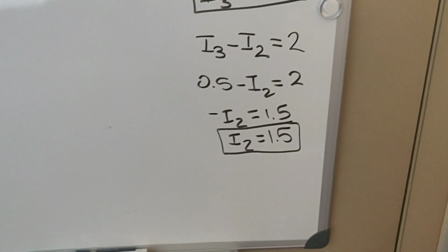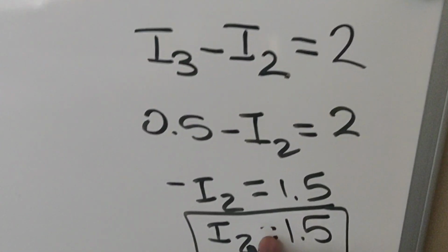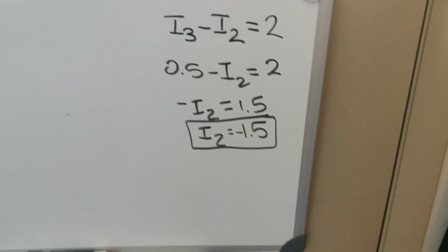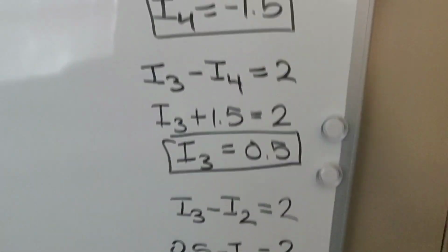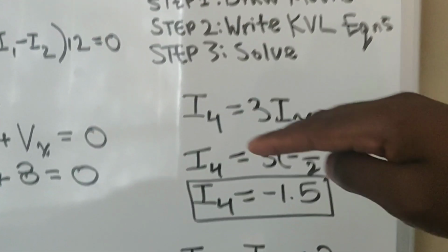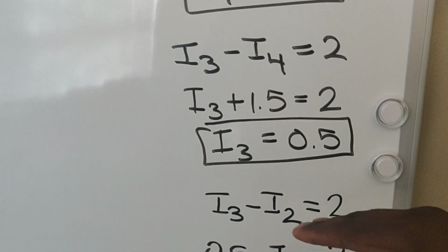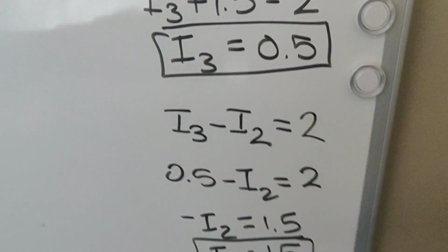Yeah. So I went ahead and just finished a little bit of algebra on that, and we finally come to, actually, this is a -1.5. So we finally come to what we needed. We found what I2 was after starting back from I4, analyzing the circuit, and drawing equations to solve for the unknowns that we needed to get to where we know I2 now.